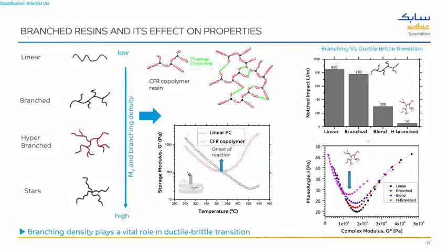So how do you characterize this crosslink? If you take a rheological method, put a sample between these two plates and do a temperature ramp going from 280 all the way up to 420, you can see this particular special PC copolymer likes to build viscosity or modulus so that it can stop the flame propagating and act as an anti-dripping agent, whereas a standard polycarbonate would decrease its viscosity and modulus as a function of temperature. Only at a certain temperature does it begin to decompose. And this is the melt state.